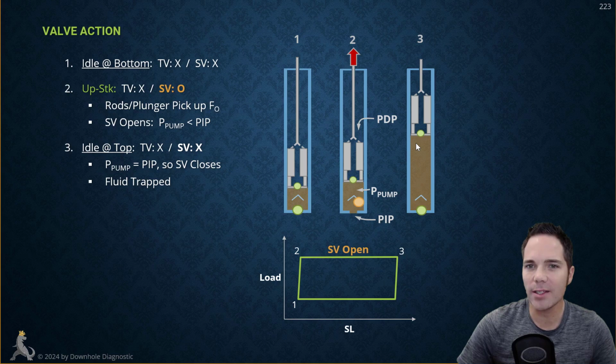At this point right here, this is when the fluid that was getting sucked into the pump, who thought, hey, this is pretty cool, look where we're going, all of a sudden the trap door closes, right? And that fluid that got sucked into the pump is now trapped. It's got a closed standing valve on the bottom, and it has a plunger that's about to come down and compress on it to pressure it up. Right now, the fluid is at very low pressure, whatever the pump intake pressure is, but we have to pressure it up greater than the pump discharge pressure.